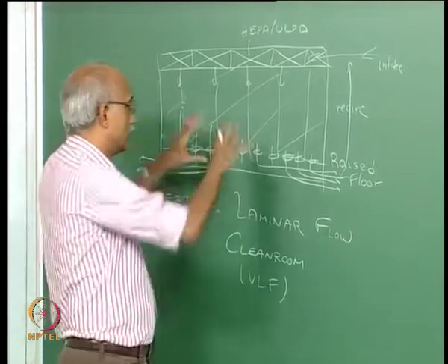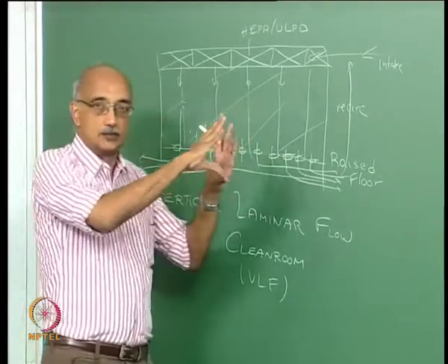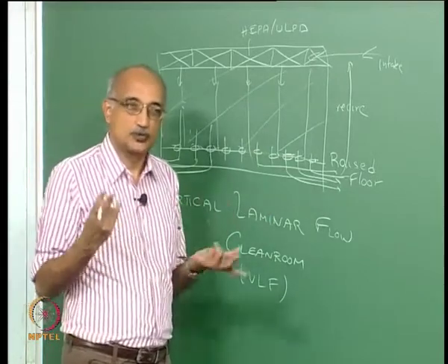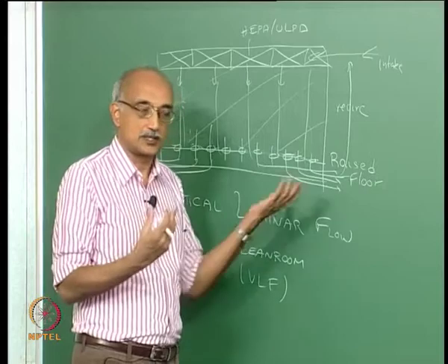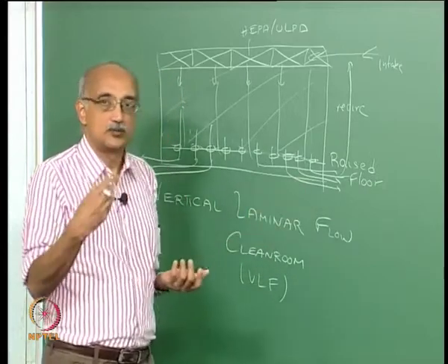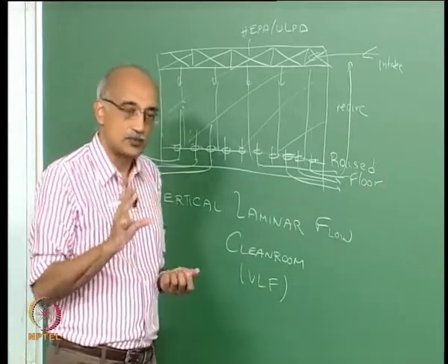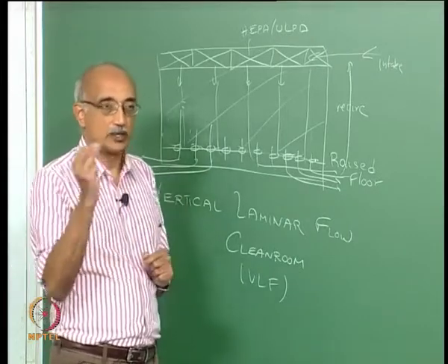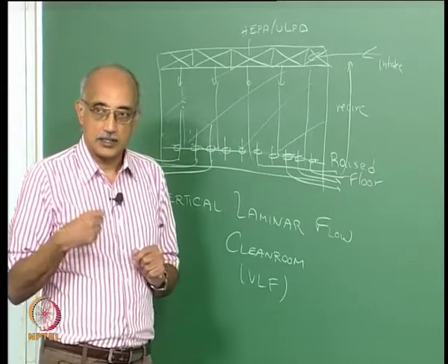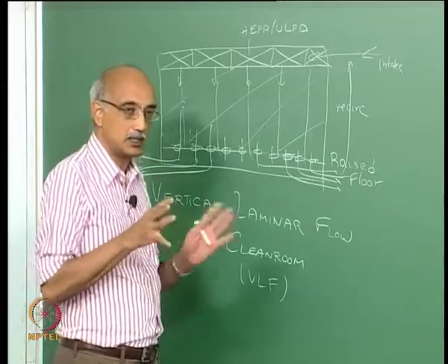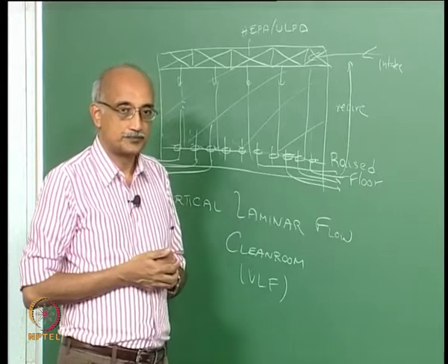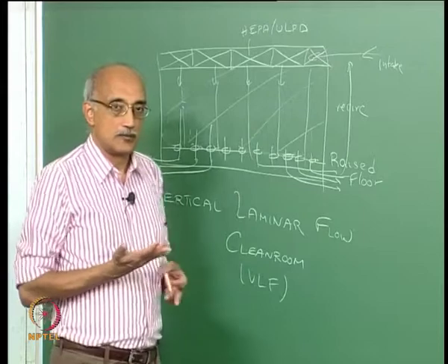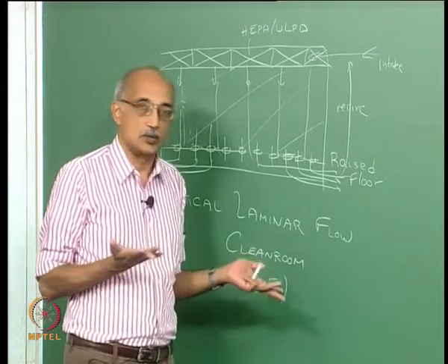You have essentially a fixed control volume, which is a clean room that material is entering and leaving. And it's essentially a two-phase flow. You have the gas phase, in this case air, and you have entrained particles in it. Now depending on the size of the particle, some of them you may treat as single phase, but as the size of the particle becomes larger, you have to treat it as a multi-phase problem. So it's kind of a combined single phase, multi-phase problem. And there are classical methods of solving this problem. You can essentially write down the conservation equations.